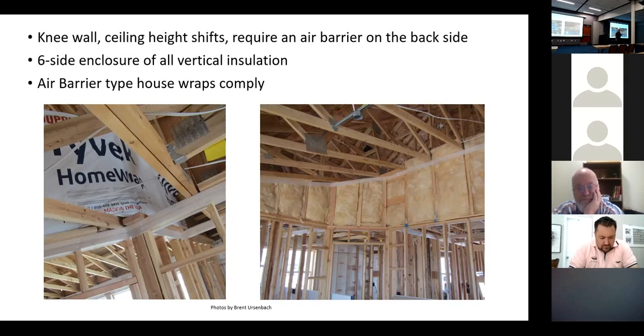Yeah, for an unvented. So that would be 3 inches basically of closed cell foam. Yeah, basically 3 inches of closed cell foam, then you can net and blow and fill the rest of it up. Or you ventilate it, putting baffles in. You'd have to baffle the whole length of that wrap.